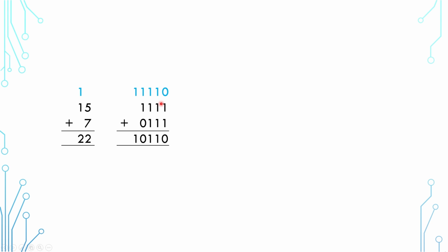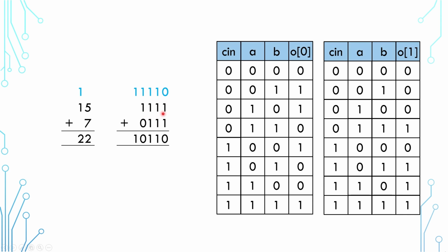What it really means is that the previous truth table is incomplete. To make it complete, there are actually 3 inputs, the 2 numbers A and B and a carry in. Now once again, if this is new to you and this is totally confusing, I'd recommend going through the truth table and using a method called Karnaugh map to come up with the digital circuit. But for this introductory video, I'm going to use intuition to create a circuit based on what we already know.